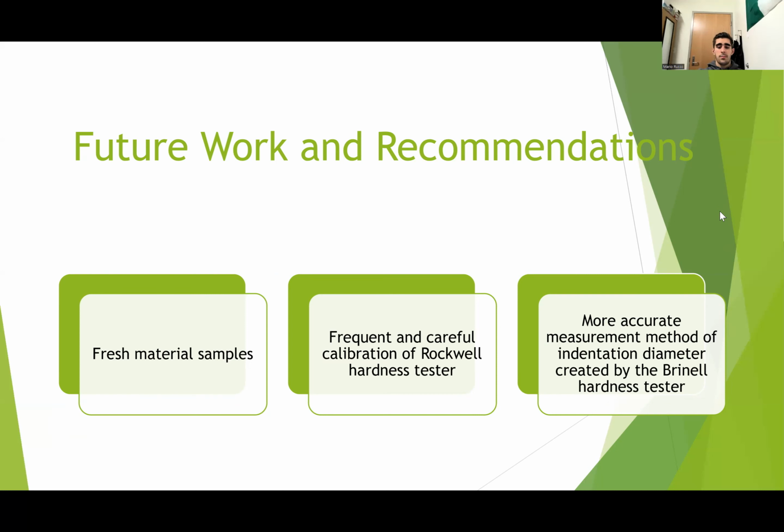I would like to add that while the data showed that the heat treated steels were softer than the untreated steels, we still got the right correlation that the oil quenched steels were still harder than the air treated steels, which is what we expected, and that still showed itself in the data.